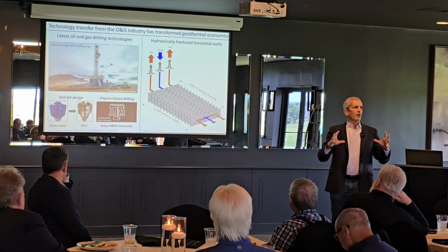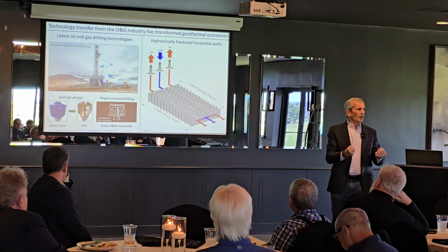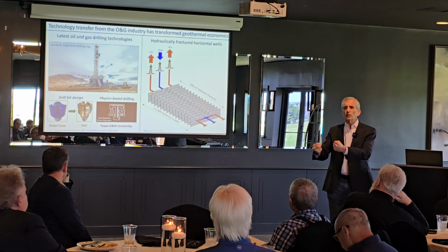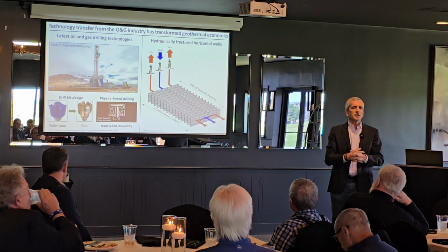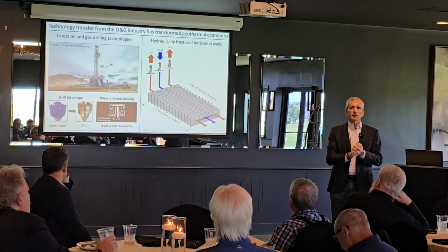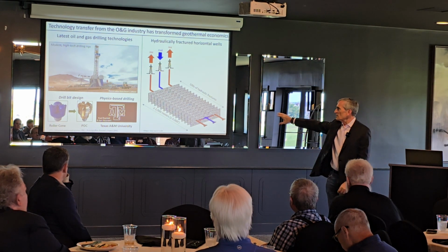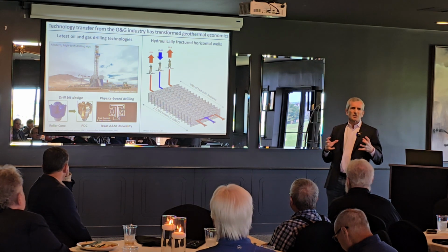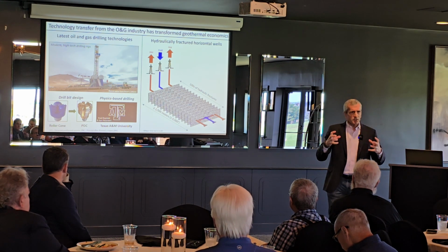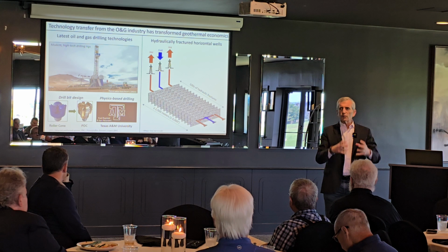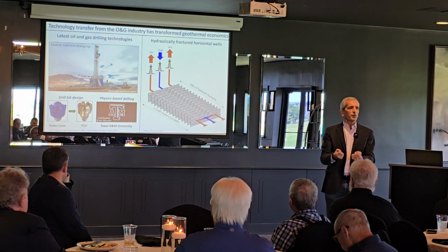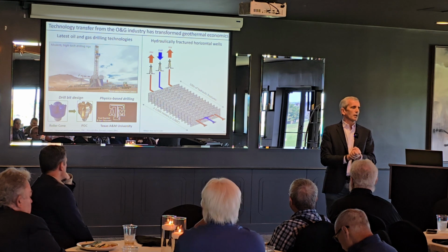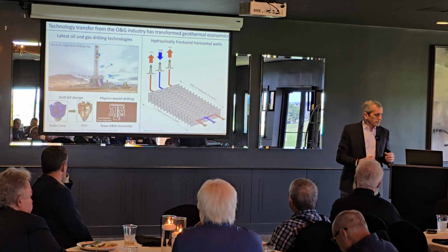There were all kinds of paradigms about how in hard abrasive rock, like what you drill through in geothermal, you're never going to be able to use a PDC bit. Well, guess what? Those PDC bits work way, way better than the approaches used in the past. And then something called physics-based drilling, which is really simply understanding how you take all of the elements of the drill rig, the drilling machine, if you will, couple it with the type of rock you're drilling through, and come up with the best approach for drilling a particular well. With all those things together, we've made some incredible advancements.